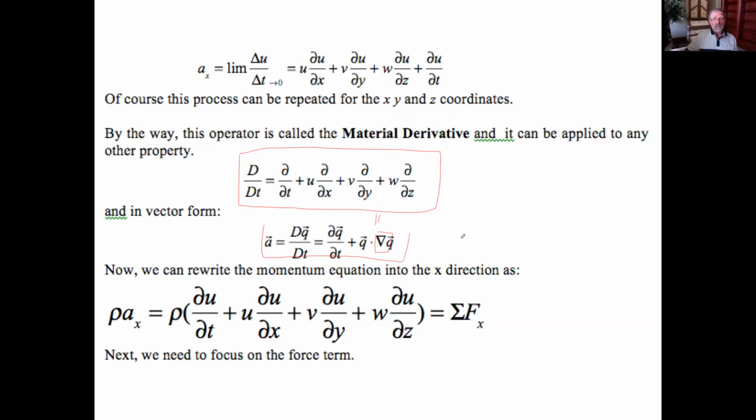So we started with momentum equations, and let's remember that. What we did so far, we said rho times acceleration. I convinced you about this. This is the acceleration. It must be equal to sigma F, the forces acting on that little cube element. So the next task is to figure out what the forces are. Okay, let's do that. How are we doing? Doing okay.